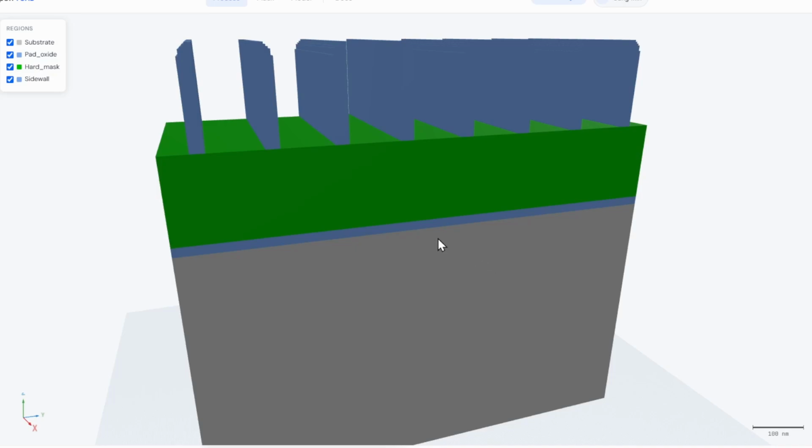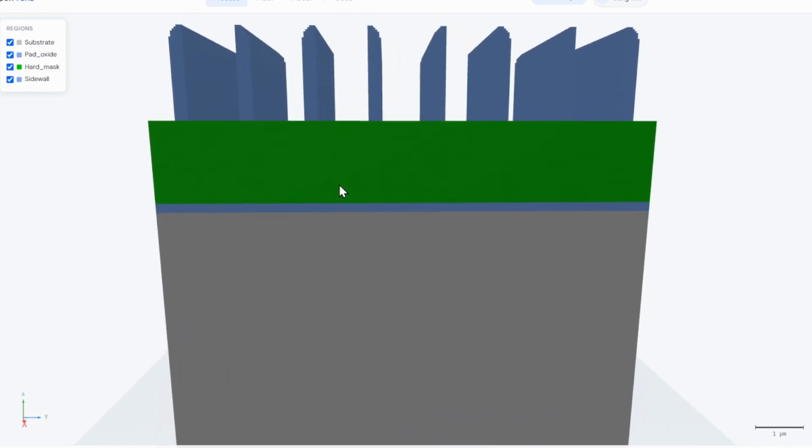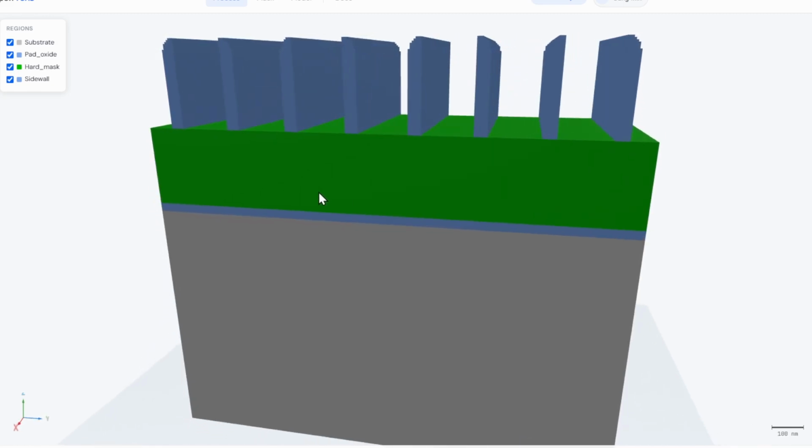Now only silicons are etched away, so now you cannot find anything corresponding to the mandrel. Mandrels are gone. And how can we save our hard mask shown here? It is because when we etch away this silicon, once again, silicon nitride and silicon have quite different etch rates, so it is not damaged by this silicon etchant. So now we have a very clear pattern shown here, and its thickness is just given as 7 nanometer.